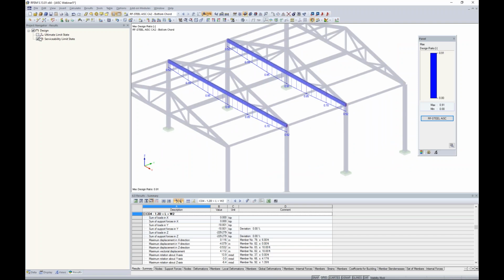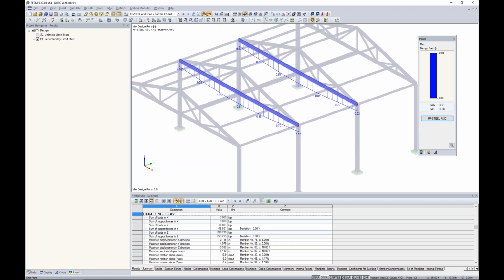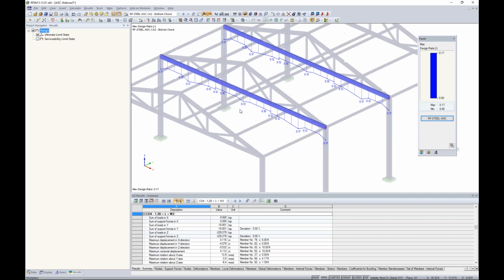out. Well, this looks like our serviceability limit state design according to our ADA module, and the results are identical, which is exactly what we would expect. Same thing goes for the ultimate limit state. We can see here we have these same numbers along the length for both bottom chords. So again, different approaches, but you should come up with the same results. Again, you have to pay very careful attention to things like unbraced lengths.